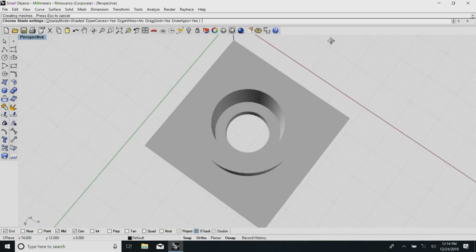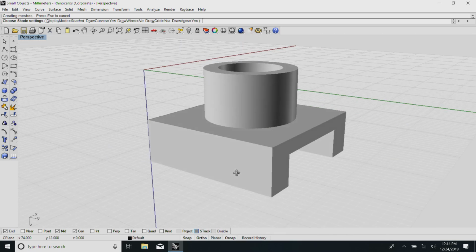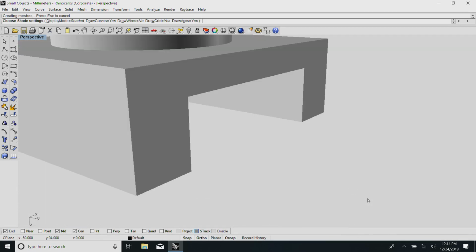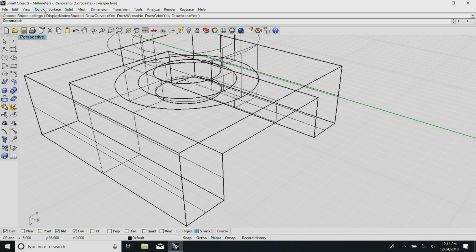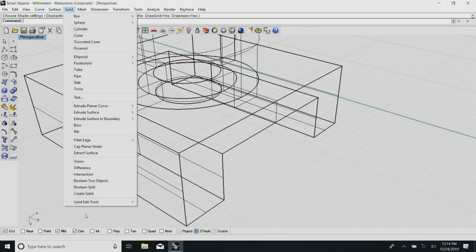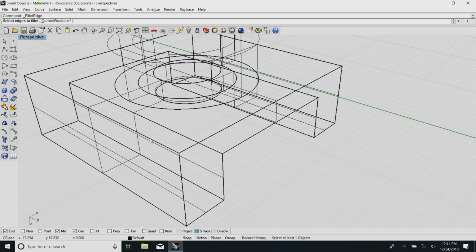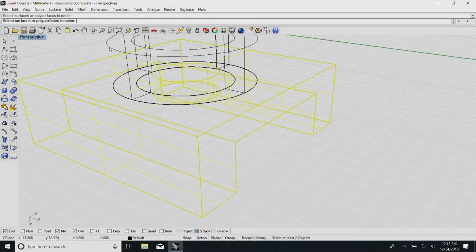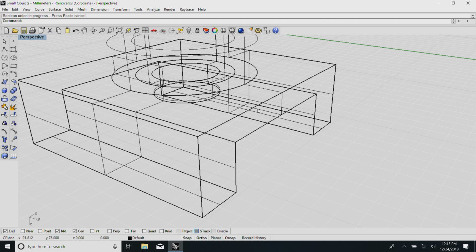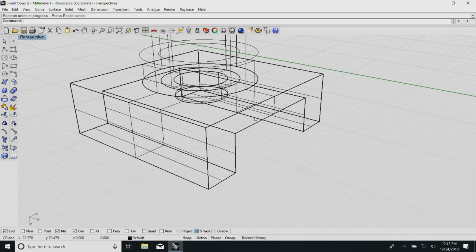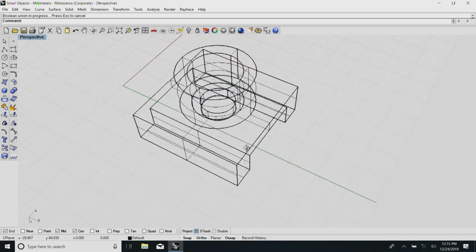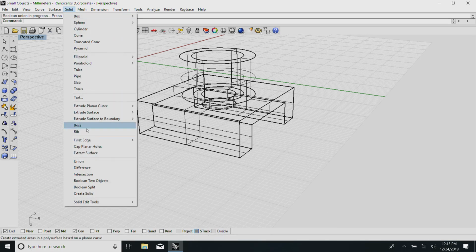You have seen this, and in this case comes the quite important thing, this is where our CAD packages are able to really make a difference, where I can do a filleting which is equivalent to the welding operation that we carry out. Actually complete the boolean, now it has become a genuine full-fledged solid. Now, when I do the filleting operation, see what will happen.